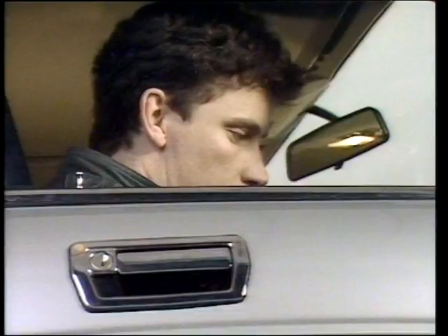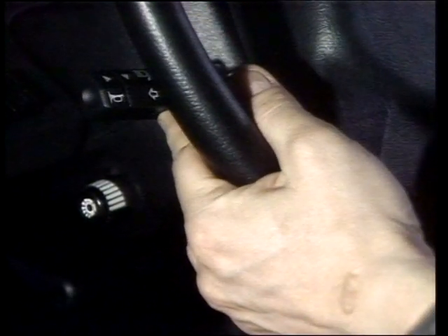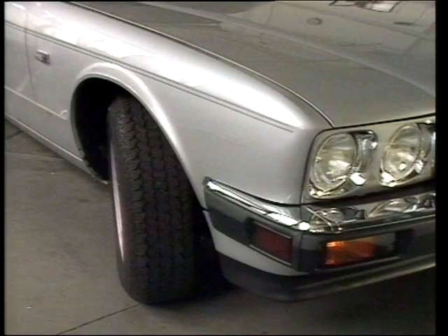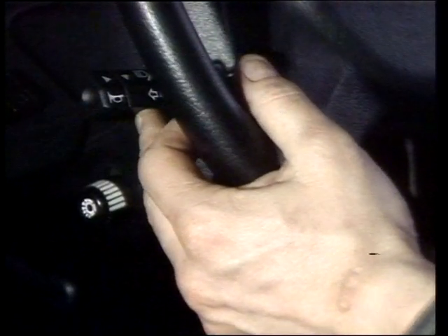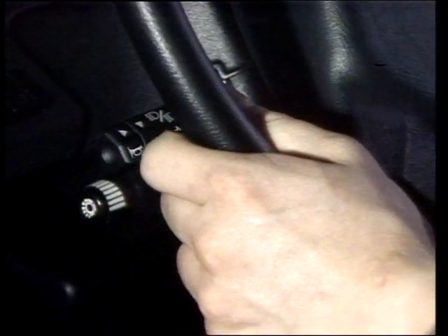The direction indicator system includes a lane change facility. If the indicator switch is held in position for longer than 3 seconds, the CPU will not monitor the reed switches. Cancellation is achieved simply by releasing the switch.